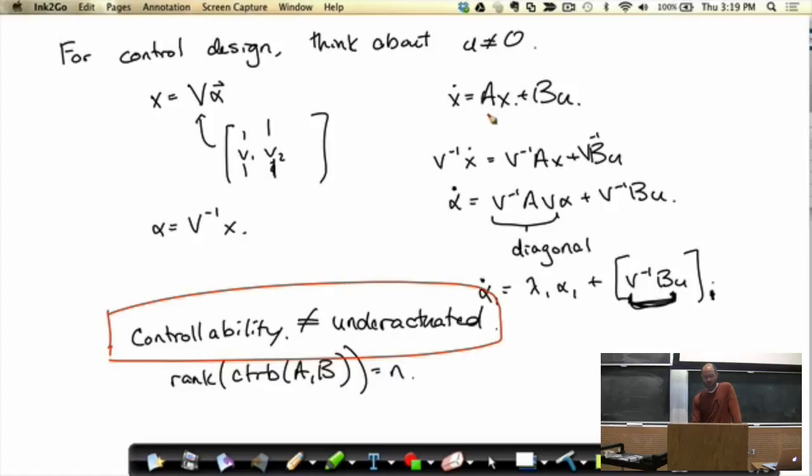So there's a degenerate case where you get some zeros in the eigenvalues of A, which would be neutrally stable, right? The nonlinear system could actually be stable, or it could actually be unstable. You can't tell because the linearization happened to go to zero around there. Yeah? Okay.